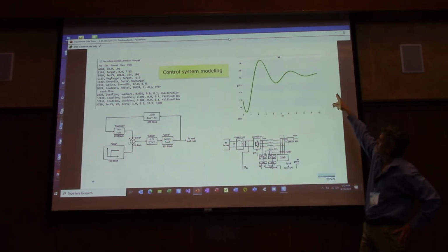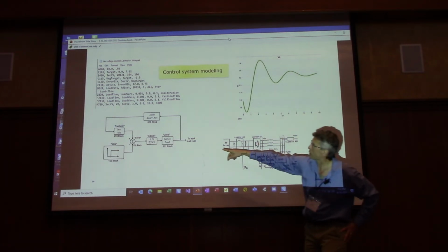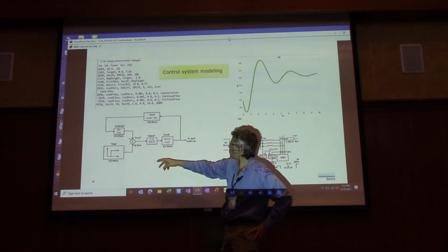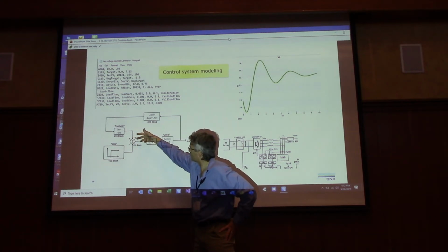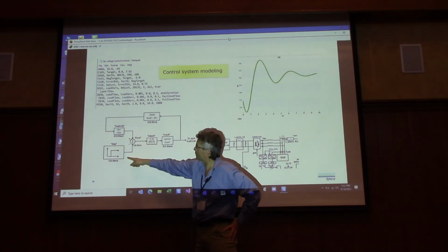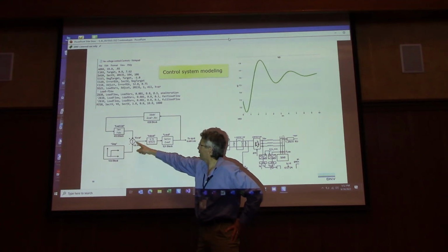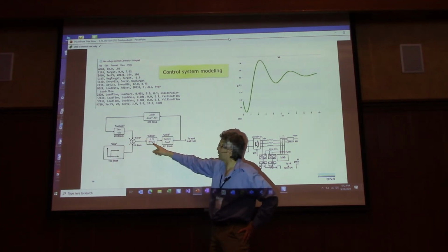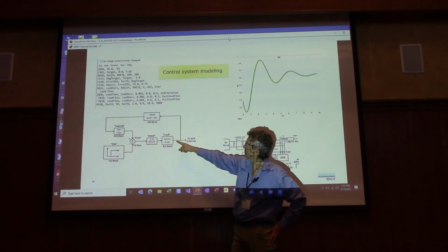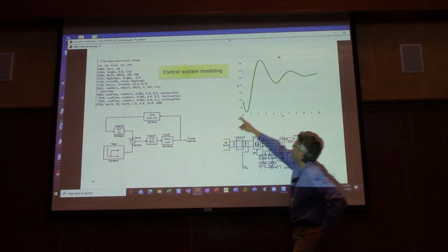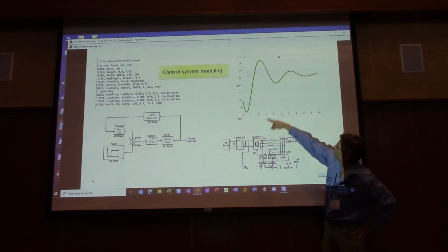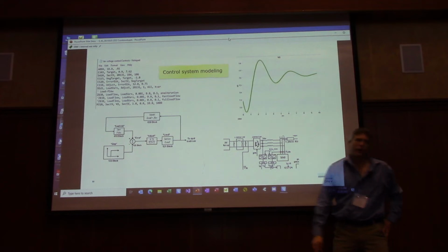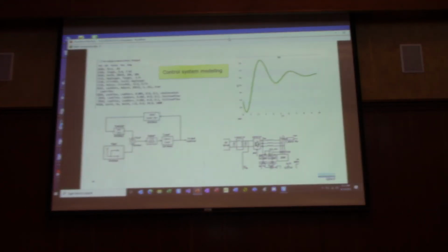And this is a run from Synergi for a StatCom. So we've got model load coming in here, and voltage. We're looking at the voltage compared to this step signal, and this is an error. We're running it through this integrator. That's adjusting our VARs, and it's going to a spot load. So you can see this thing had a set point of, this is in kV up there, but you can see it oscillating and bring back the horrors of controls, EE301 or something like that, right?